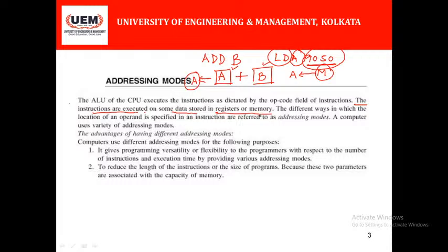So how does the opcode field of the instruction describe the operation performed? Look at that. The opcode field of this instruction is representing LDA instruction, and the opcode field of this instruction represents ADD instruction. So we perform the addition operation here, and as it's a load instruction, we perform the load operation here.